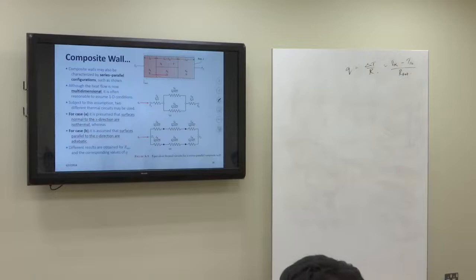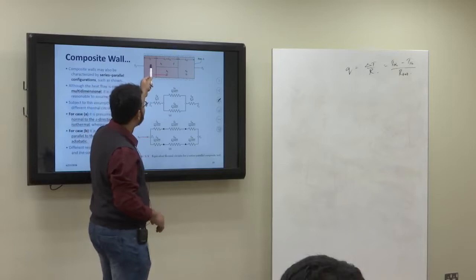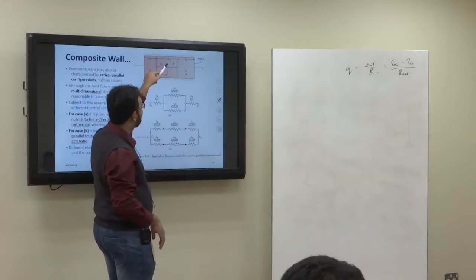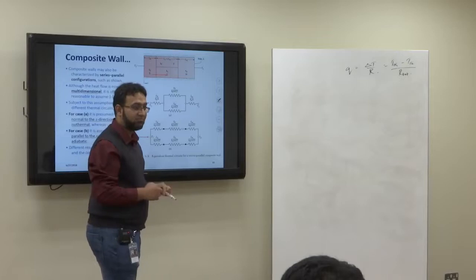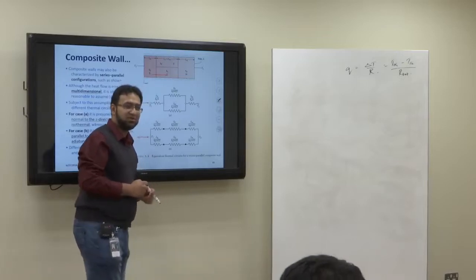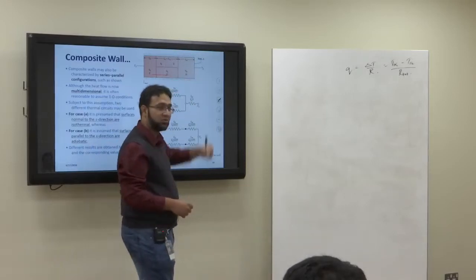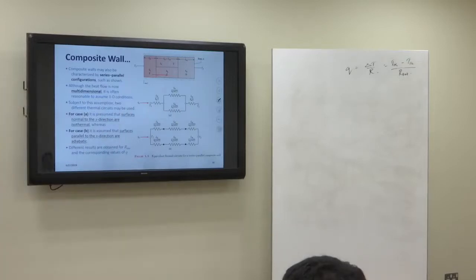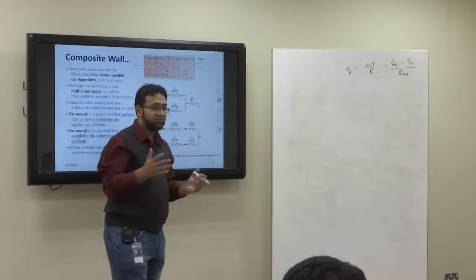The heat circuit here will be a bit complicated because there is a possibility that the heat transfer will occur from the wall E to the wall F and the wall E to the wall G, but there might be heat transfer between F and G as well. Then it does not remain one-dimensional flow, then it's a two-dimensional heat transfer. Then there will be heat transfer between G and H and F and H, right? Anyways, we can still solve it using one-dimensional, but if we have to solve it using the one-dimensional case, we have to make an assumption.